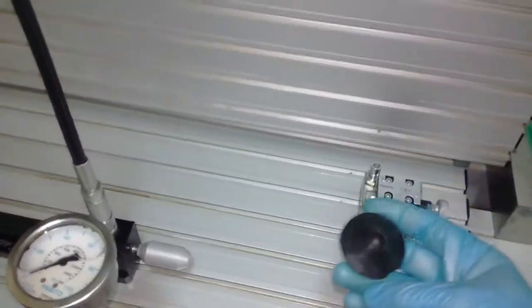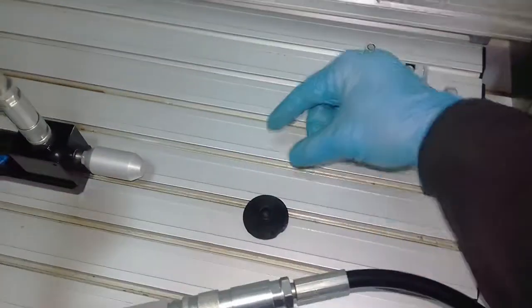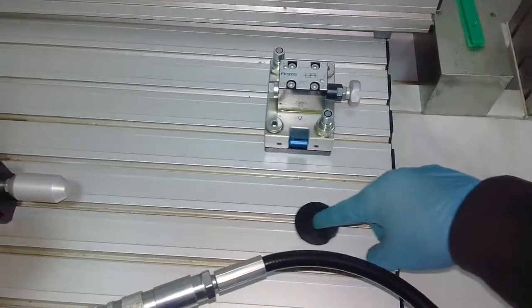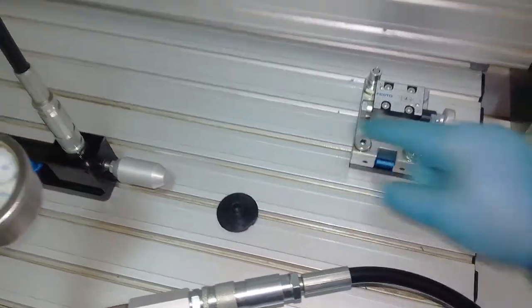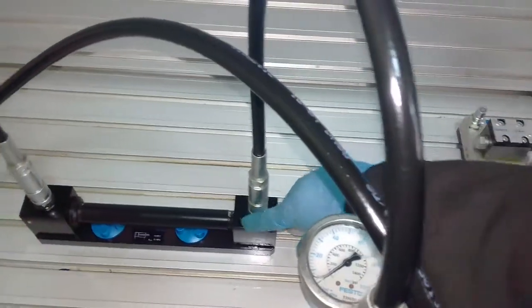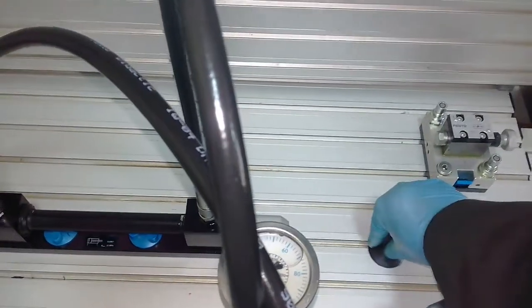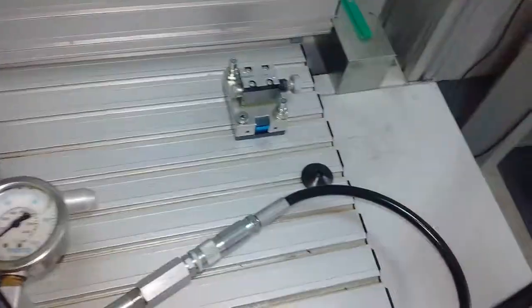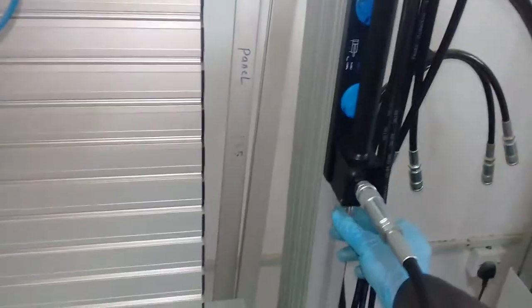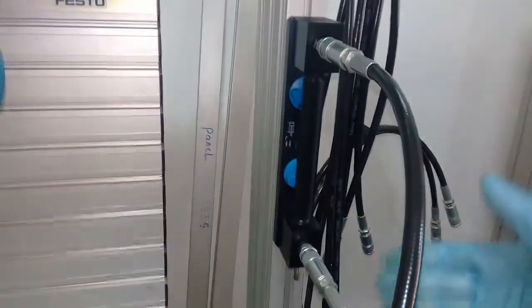As you see here, if we have a manufactured piece like this, we want to move it on a production platform, then we should push it by a horizontal cylinder. This double acting cylinder would push this manufactured piece on the production platform. Then we will press it by this vertical cylinder.